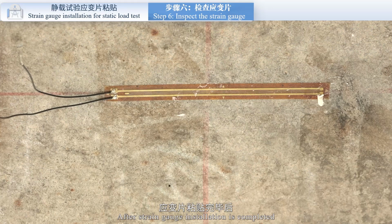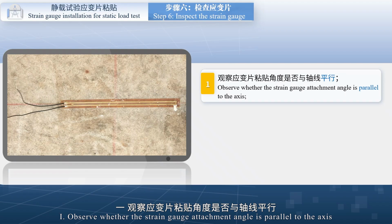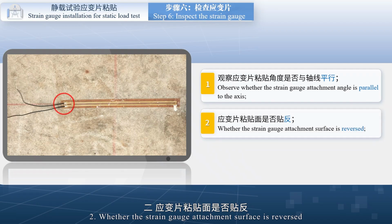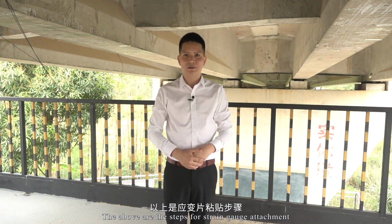After strain gauge installation is completed, we inspect the strain gauge. The inspection steps are: first, observe whether the strain gauge attachment angle is parallel to the axis. Second, whether the strain gauge attachment surface is reversed. Third, whether the strain gauge is firmly attached. The above are the steps for strain gauge attachment.